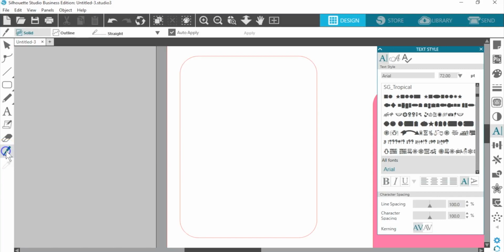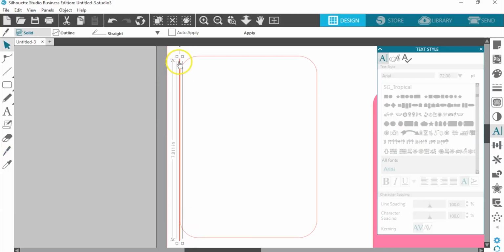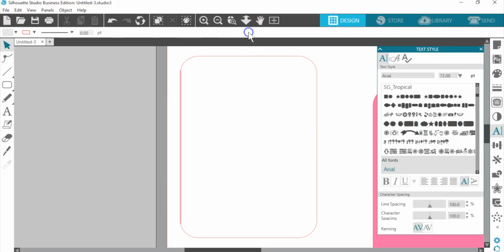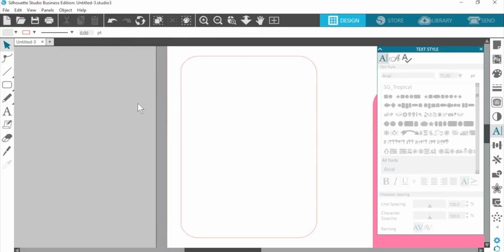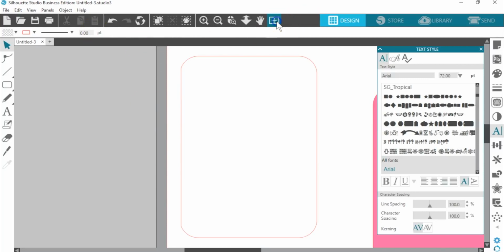So grab the knife tool on the left, choose Treat the Shape as Solid, and this time I want to uncheck Auto Apply. That means when I draw my knife line, again hold Shift while you're dragging to get it perfectly vertical. So instead of automatically cutting where that is, I can use my arrow keys and position that knife line where I want. And so it's just barely overlapping, and now I can click Apply. And that has trimmed off that little edge, and we can delete that.